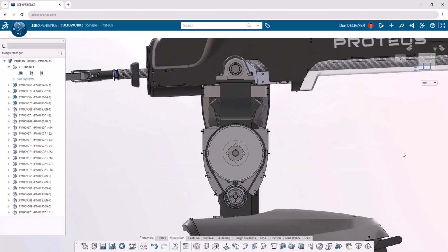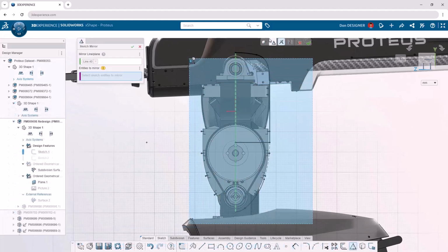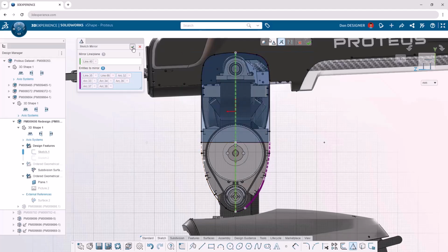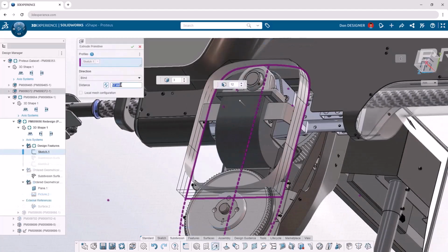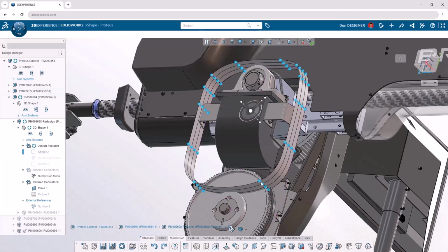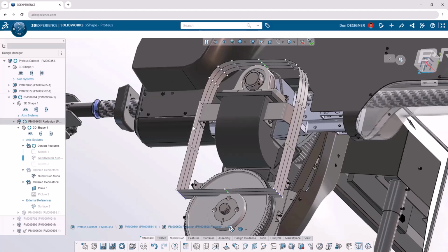Now, 2D sketches can be directly converted to subdivision geometry with an extrude primitive command. This is a more precise way to generate your subdivision shapes, and it immediately launches you into the subdivision environment, so all your sub-D commands like crease edge, symmetry, fill edges, and more are at your fingertips.